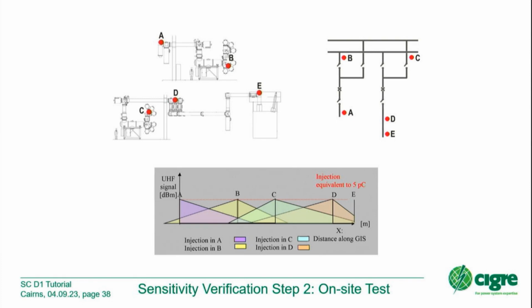And the theory is that the frequency emission was actually in the VHF, not UHF range, because of the positioning of the void and the type of void that it was. Therefore, the system wasn't detecting it because it was looking in UHF instead of VHF, and also because the propagation of such a lower frequency signal is different through the GIS. So I suppose my question is: is UHF the right band to be looking at? And is there any consideration for modifying the frequency ranges based on newer geometry GIS with more compact designs?